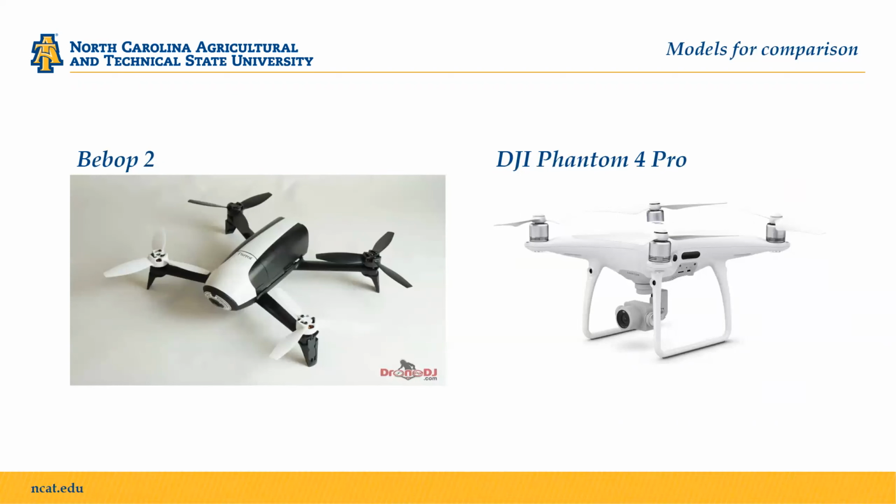We will compare two models of unmanned aerial vehicles, the Bebop and the DJI Phantom 4 Pro, for differences in the big three: communications, hardware, and software. In communications, the Bebop memory is accessed through its Wi-Fi connection and the use of communication protocols such as Telnet and FTP. The onboard flight controller controls the drone by combining input from several sensors, including a GPS chip, a vertical camera used for adjusting the Bebop drone's orientation and its XY position, and other sensors such as a barometer, accelerometer, and a magnetometer for assistance.